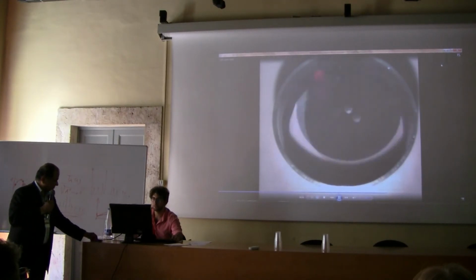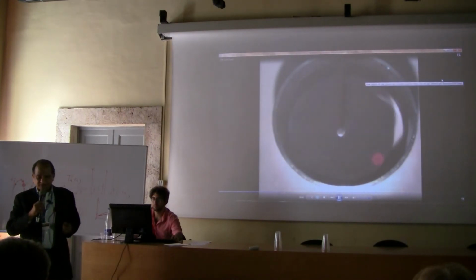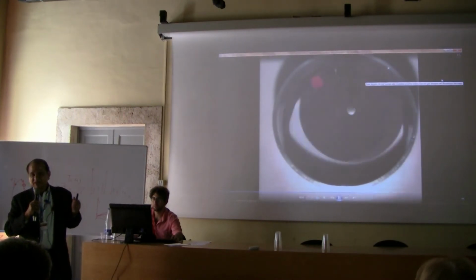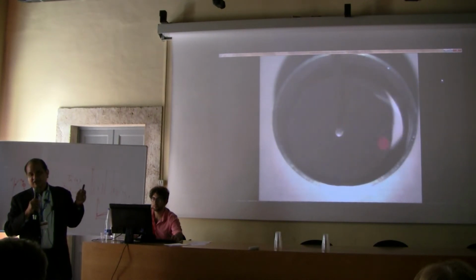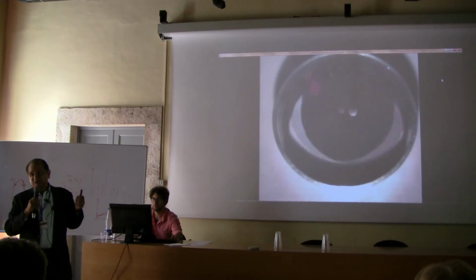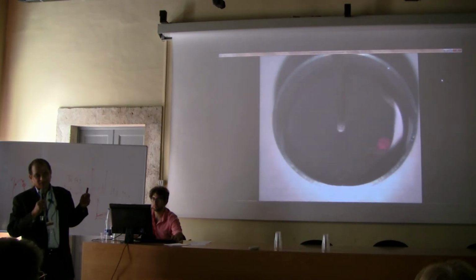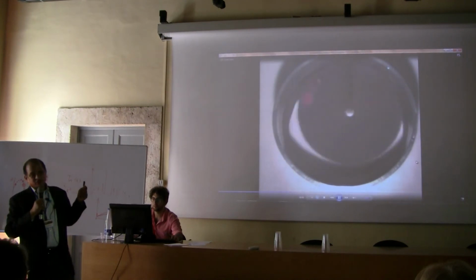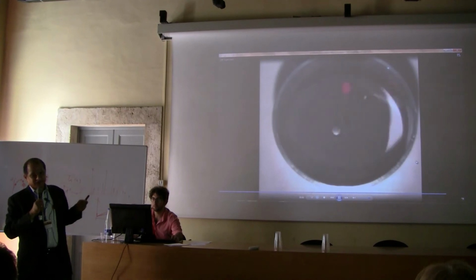Yeah, so in this case, it's a dangerous state, so you could see that you have a low frequency input, but the response has a high frequency. So this is an example where you have a low frequency energy input into the system being converted into high frequency doing backward whirling. Obviously this is a state you'd like to avoid because it could lead to breakage of the drill string itself due to torsional failure.